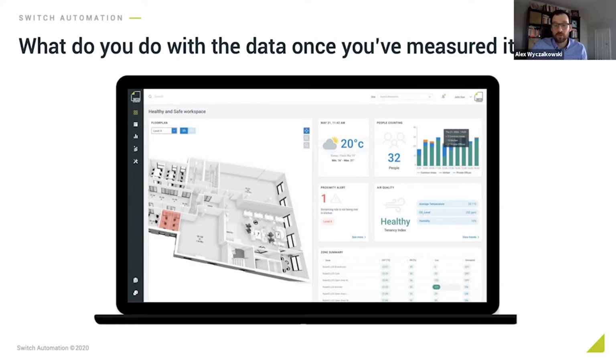And again, like we said, this specific focus on IEQ, indoor air quality, is going to change the way you act. So you're going to ventilate more, filter more, humidify more, whatever the data tells you you need to do. Or maybe you need to change your occupancy requirements. Maybe you thought you could have 50 people in your building, but after looking at the data, you said, hey, we can't get CO2 where we want it with 50 people. So we've got to limit it to 30 people if you have a retail space, something like that. So again, using data to help drive decisions, and in the end, in this case, to keep people safe.